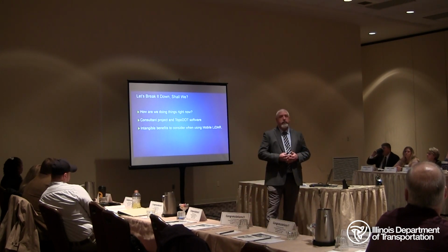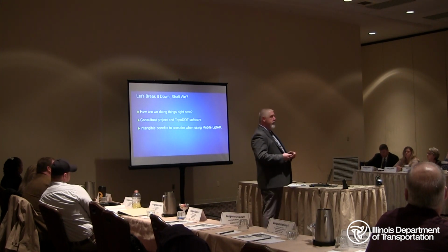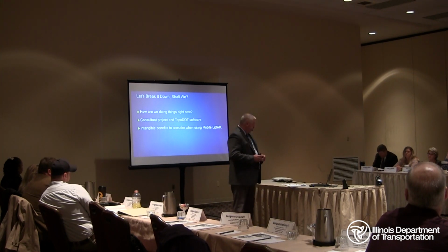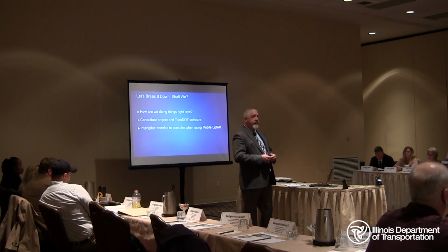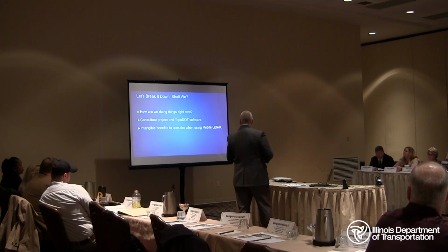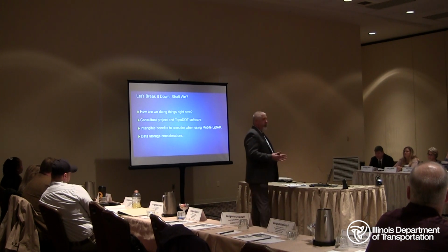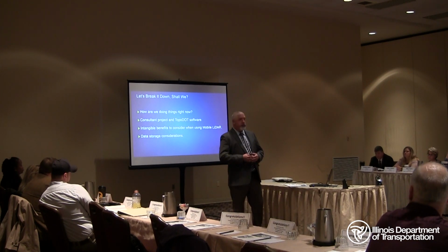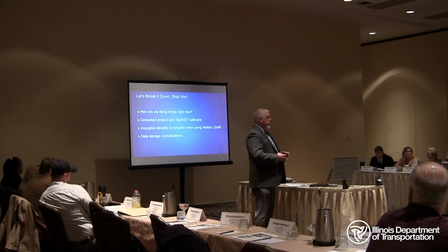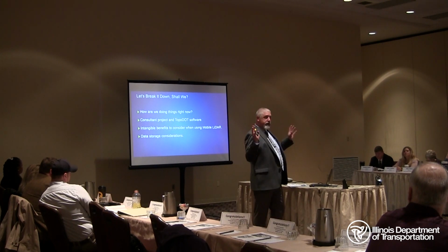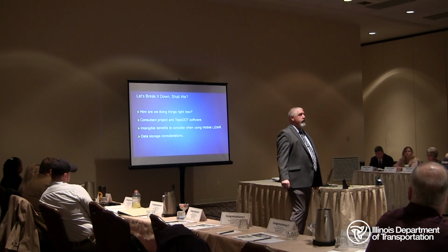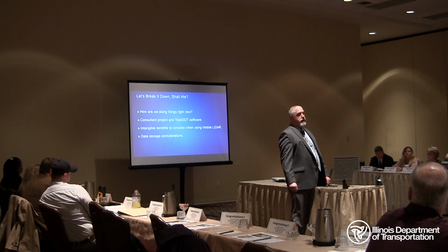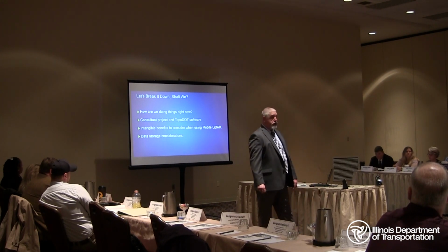Intangible benefits to consider when you're looking at mobile LIDAR. The things that maybe don't come immediately to mind. You know, one of the most important of those would be safety. Safety for surveyors in the field, both IDOT staff and consultants. Data storage considerations. Sometimes this gets overlooked. When you look at those pictures, when you think about that 3D model, those are huge, huge files, big data. So a lot of thought has to go into the hardware and software needed to store and run that data.